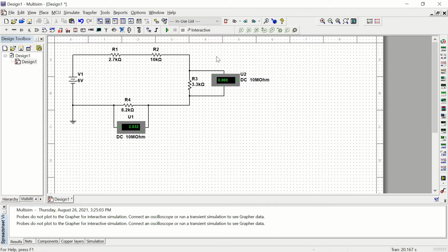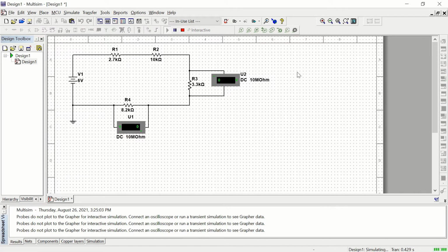And you want to have that over the resistor, and then now it will simulate it, and you can see how much voltage is dropping over that. So you're going to measure the voltage over each resistor. Notice how I'm saying you're measuring the voltage over, like you're hovering over the resistor. You can't see what my hands are doing because I'm screencasting this, but you hover over it and you measure it on either side. Okay, so that's what that's going to look like, and then you'll do a screenshot of at least one that looks like this and paste that into your document.